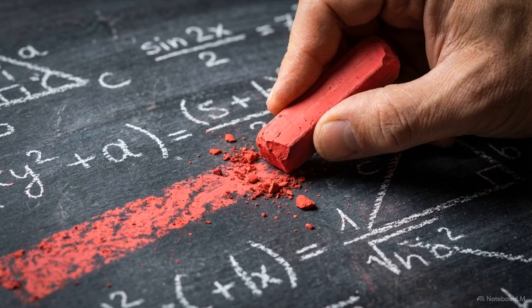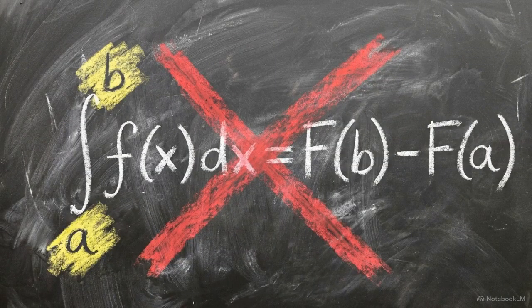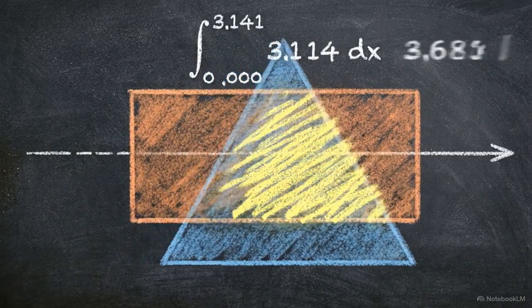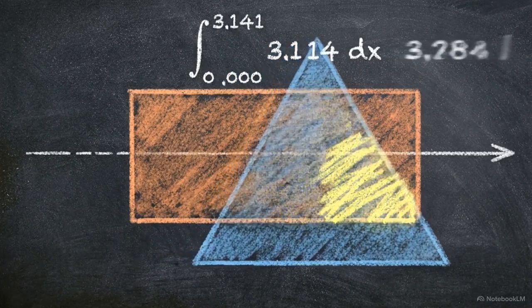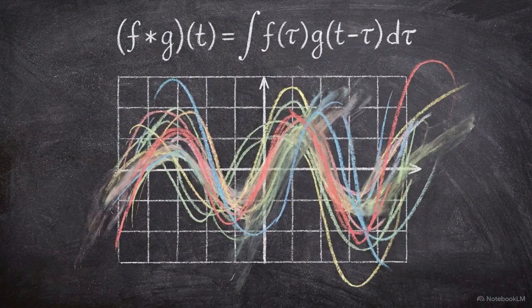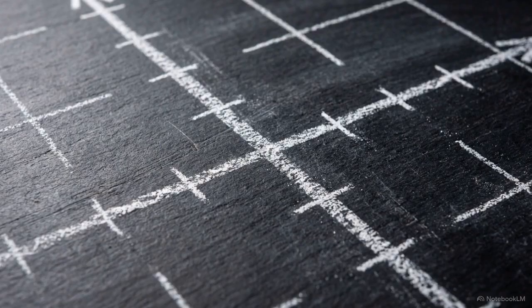The most common failure point in exam analysis happens right here. Students will try to evaluate the entire process using a single static set of integration limits. The physical shape of the intersection changes continuously as the signal slides forward, meaning mathematical limits of integration must be recalculated for each distinct phase. If you apply one set of limits across the board, your output equation will describe a shape that doesn't actually exist. The entire convolution sequence is completely rigid.